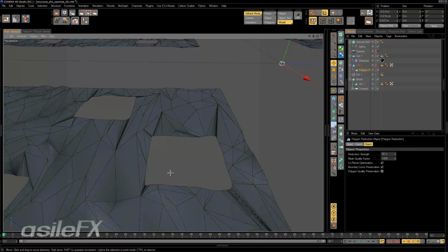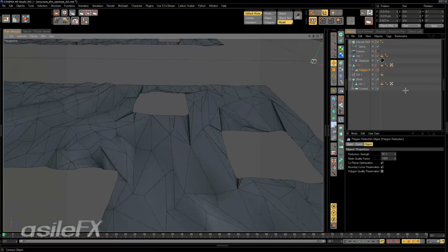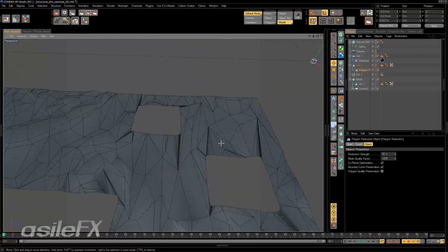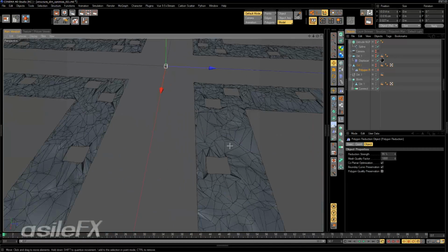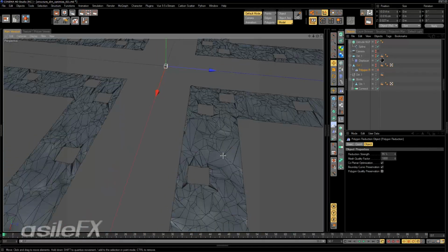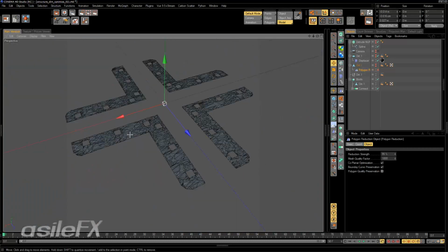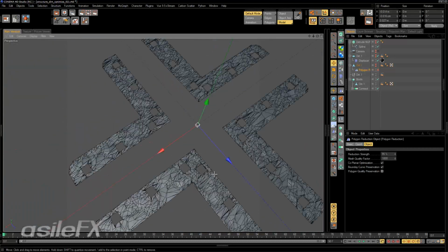There are a lot of polygons that are extra that are probably going to need to be cleaned up, or we can play around with the settings a little bit more, but mostly running a polygon reduction afterwards will take care of most of that, but still look pretty good. I chose to do the polygon reduction first before the Boolean just because it'll take a lot longer to cut out the object from a high-res object.